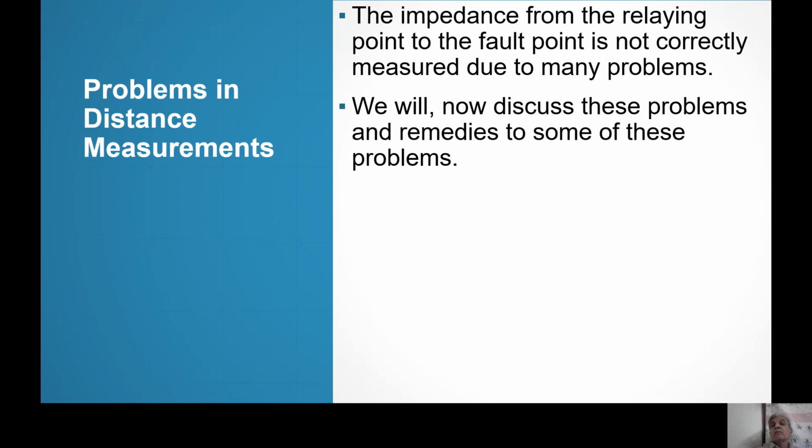You see, when a double line fault occurs, the measured impedance is the double line impedance plus the fault resistance, that is the flashover resistance. Well, that you may forget because that is just 2 to 4 ohms. But when a line to ground fault occurs, it is 20 to 50 ohms.